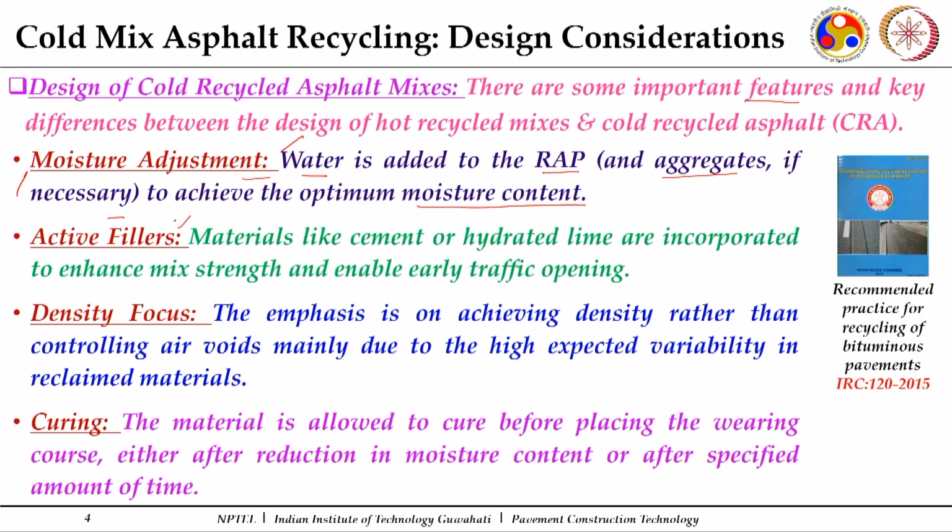Then in addition to this, specifically in cold recycled mixes, you prefer to use additives like cement and hydrated lime, because you produce these stabilized base courses, and to enhance the strength and the durability, these two additives, we call them active fillers, because they produce compounds which add to the stability. They react with the water and help in better dispersion of your bitumen emulsion also, and impart a greater strength and durability to your cold recycled asphalt mixes also.